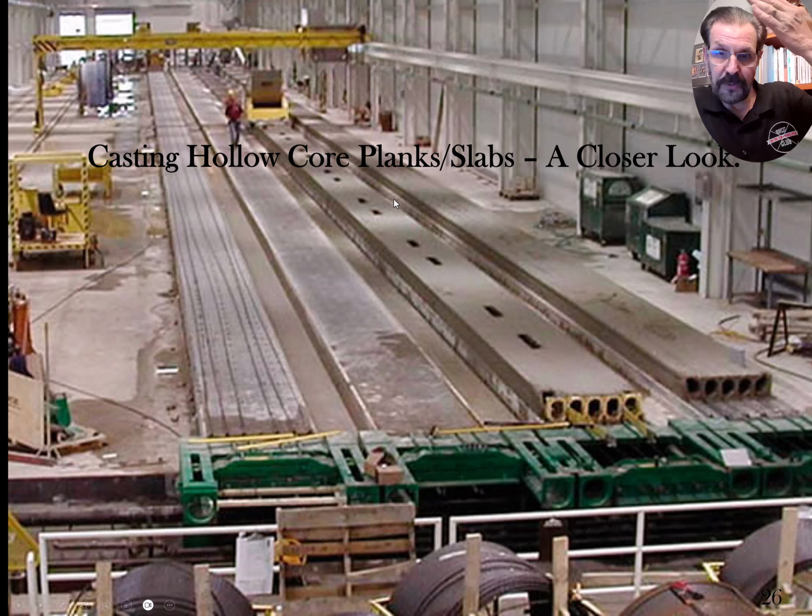And then they'll take a big saw later on that they'll run on that same track, and they'll saw cut it to the length that they need. So they actually make these hollow core slabs full length, and then they cut them. Well, when they cut them, they'll cut the strands at each end first, but they'll cut them to the exact length that they need all the way down. And so they will have thought that through throughout the whole process, of course. Anyways, so eventually they'll do these two also.